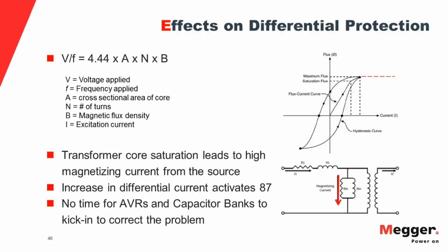Now, why we don't want differential to operate for over-excitation conditions is the question that should come into your minds. As I mentioned earlier, I'm trying to design a very dependable and secure differential scheme. Over-excitation is not an internal fault, first point. I would not like to have my differential scheme operating on an over-excitation condition because I only want the differential to operate for internal faults. Over-excitation is not an internal fault.